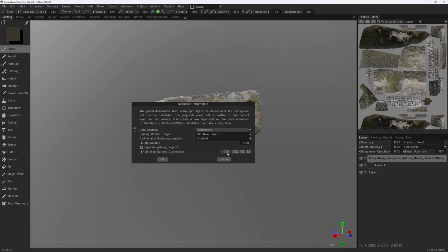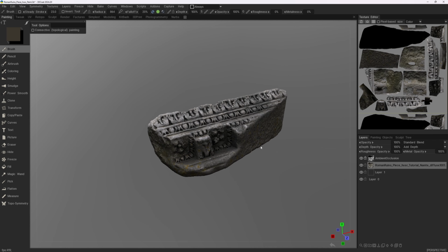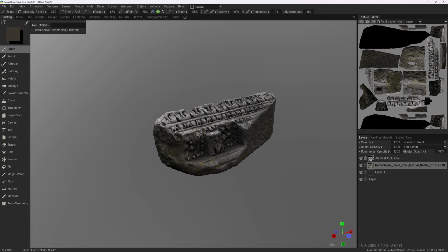And we're going to go with a 1 or a 0.455 ambient occlusion map. It's going to make it a lot darker than the linear one, and this is good because we need a little bit more of a punch to be able to light it correctly in the crevices. We will click OK, and this is going to take a little bit of time. The ambient occlusion is done, and you can see how it's darkened down the object.